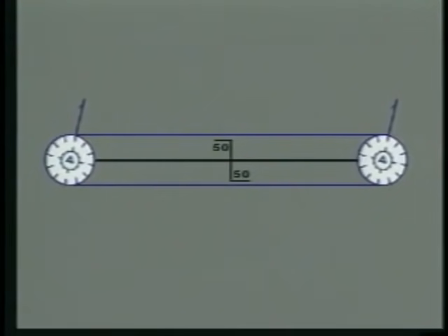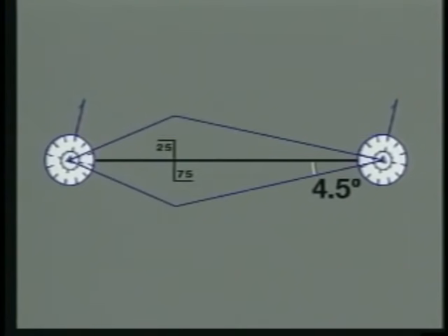The location of the changeover point can affect the shape and therefore the controlled airspace of an airway. For instance, if an airway is 100 miles long and the COP is located in the middle, then the width of the airway is 4 nautical miles on either side of the center line. By moving the COP closer to one facility, the controlled airspace changes due to the 4.5-degree angle that diverges beyond 51 nautical miles from the NavAid.